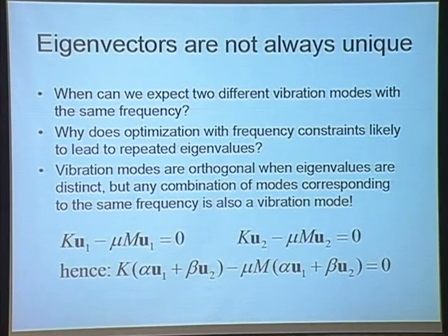In the process, you raise the frequency which is a problem and lower the frequencies that are not a problem. And so you may have started with two vibration frequencies that were 20% apart. By the time you are finished fixing the car, they are only 5% apart. And if you do the optimization really thoroughly, you can end up with them being equal.